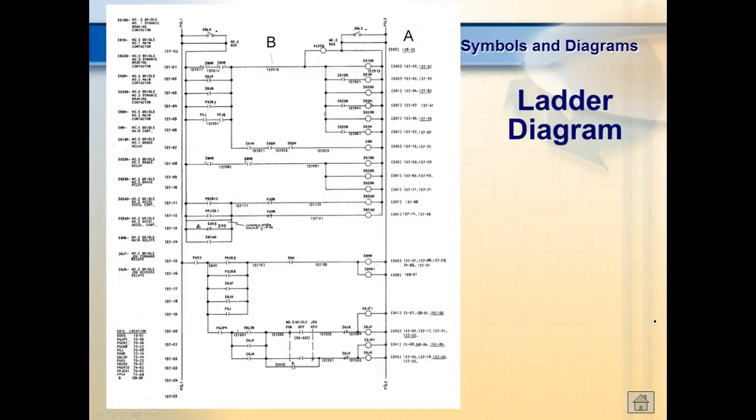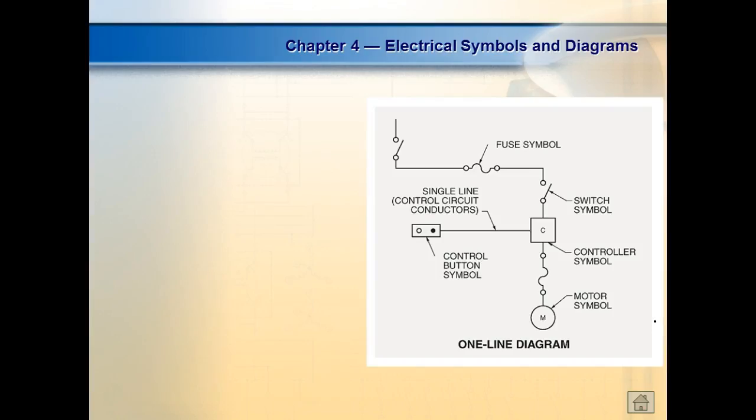So number 5, bridle reverse relay. Well, this is going to cause the motor to reverse. And if it's going to cause the motor to reverse, it's got to be controlling the motor, right? You understand that? So most of these are actually contactors. I don't know if there are any control relays in here. They're called L1 and L2, PCL1 and PCL2. These guys, by the way, ran DC motors.